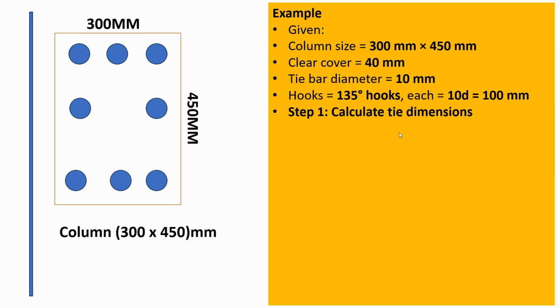Okay, voila. So now, what are the calculations? If you notice here, this column has got two sides. It has got this width and this depth. So you need to know this width, which is 300 millimeters, and we need to subtract this distance here in order for us to have this standard width for our stirrup.